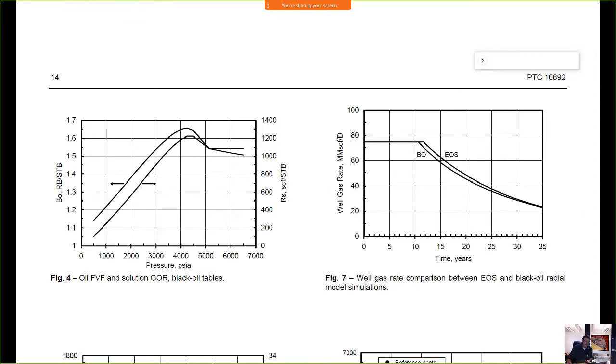You'll almost always see this for a leaner condensate. The leaner the condensate, the more, how should I put it? Let's say that we have 3 gas condensates, all with a dew point of 5,000 pounds, just like this. The one is like this, it's 30 barrels per million, lean condensate.